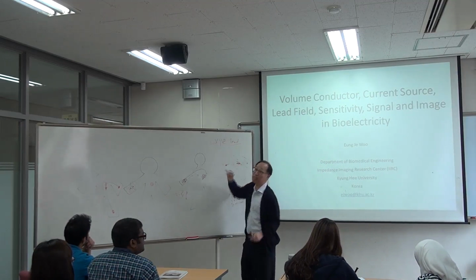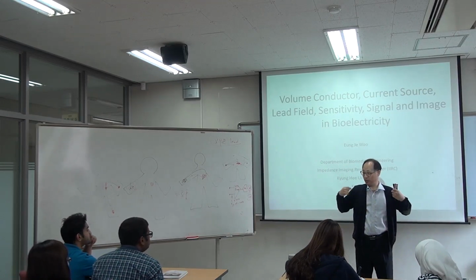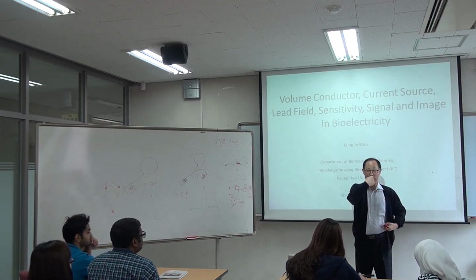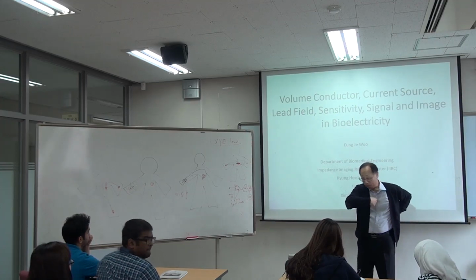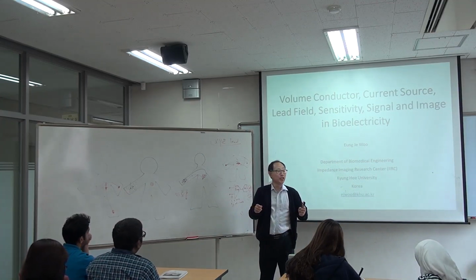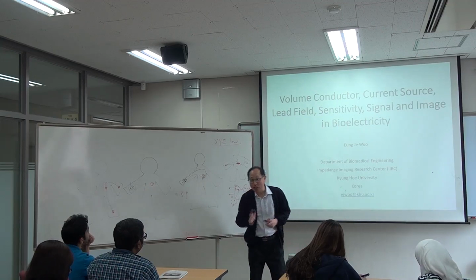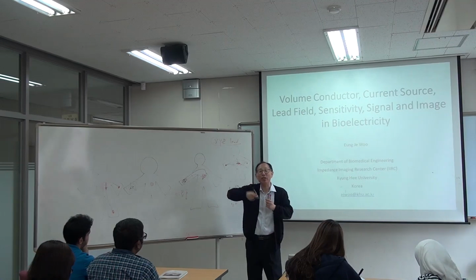In ECG measurement, you measure using 2 electrodes in this configuration, a second pair of electrodes in this configuration, and a third pair of electrodes between this configuration, one here and another there. Then, by measuring 3 channels of ECG signal, for every instant you have 3 values, right? Those 3 values will give you one 3-dimensional vector.